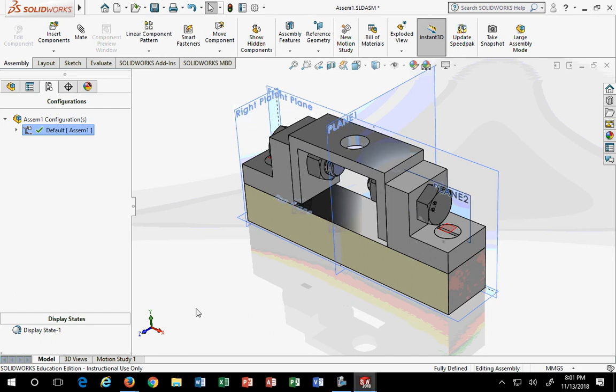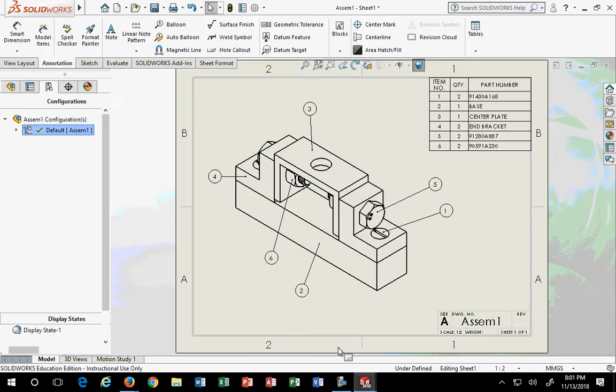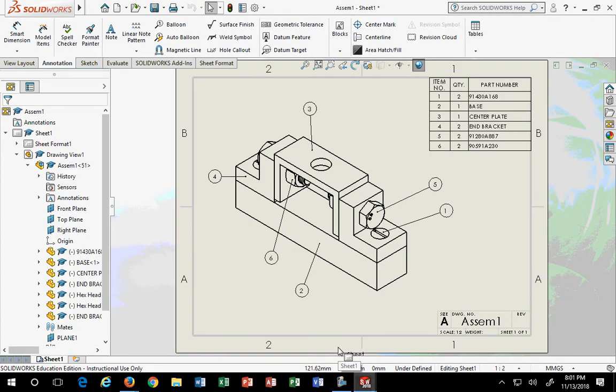So that's assembly, and this is the detail drawing of that assembly. So the same place you create detail drawings for part files is the same place you create detail drawings with an assembly. The way the balloons work is this: individual or auto, and it'll do everything, populated everywhere. Is it perfect? No. I have yet to find a program that is, to be honest, when it comes to detailing. It just does what it does. So you'll have to edit it, anticipate having to fix it.